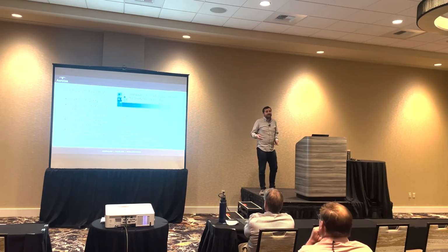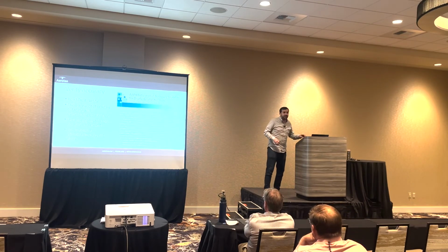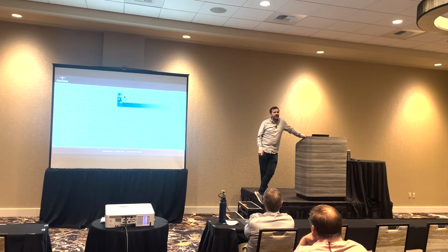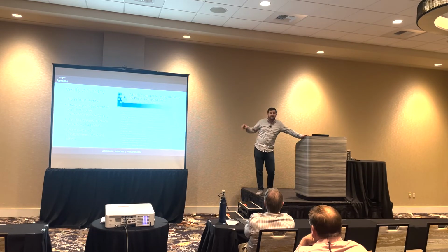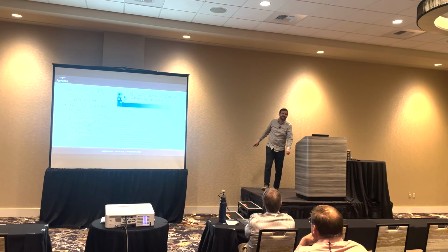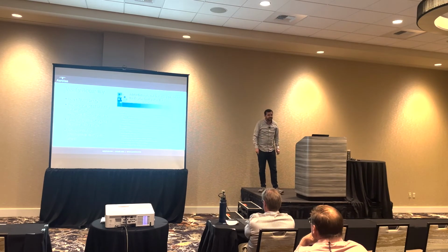As far as how to explain that to your clients, it's tough. I can try, but that's why we often say a tenth of a foot, and then just be ready if there are more questions to explain what a tenth of a foot means to you. For me, a tenth of a foot means an RMSE of better than a tenth, according to the ASPRS positional accuracy standards. Can you talk about truthing? Truthing?